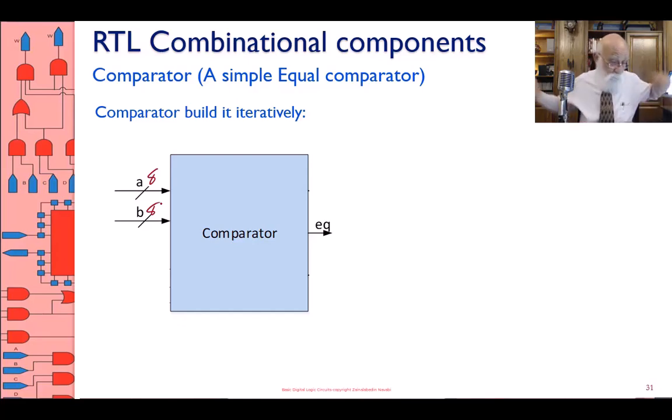How do I do this? This is a 16-bit input circuit, and then a 1-bit output. So do I generate a Karnaugh map with 16 variables and one output? The one output is good, but a 16-variable Karnaugh map is completely impossible.